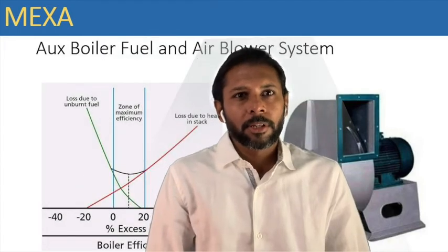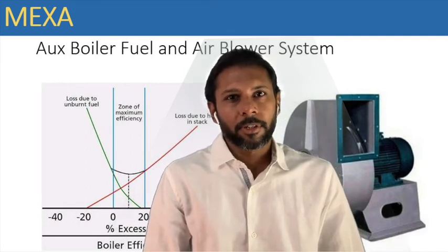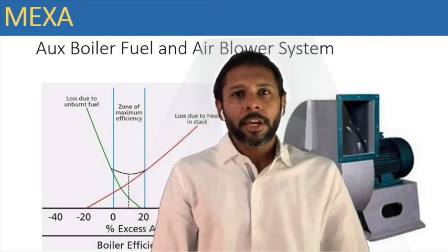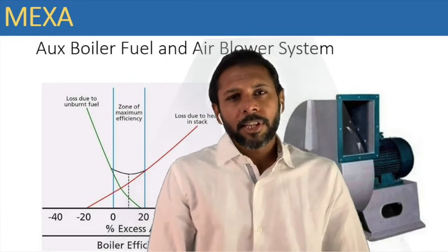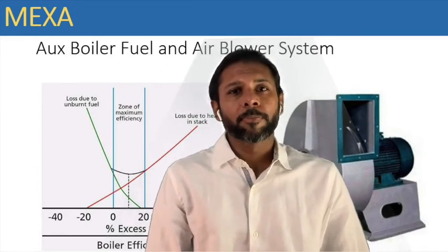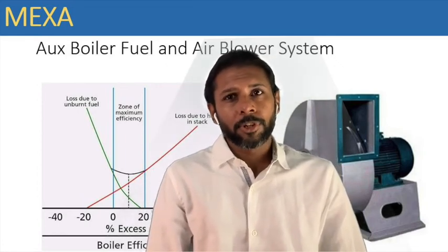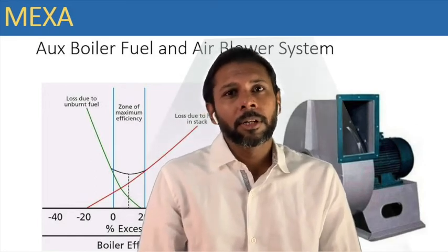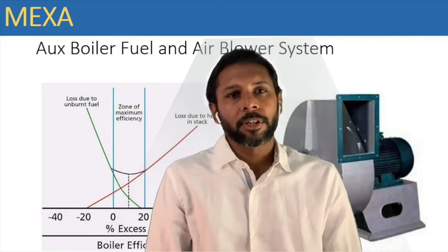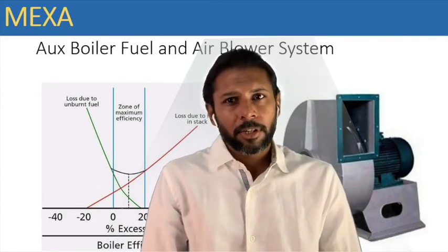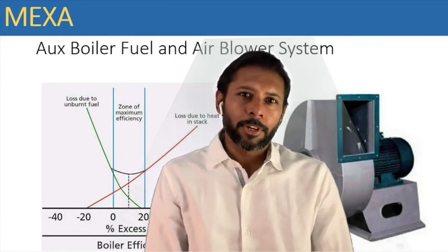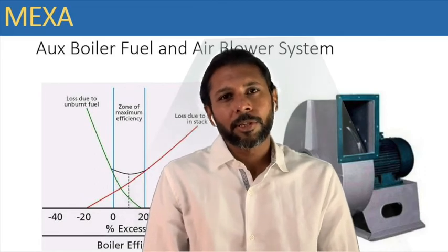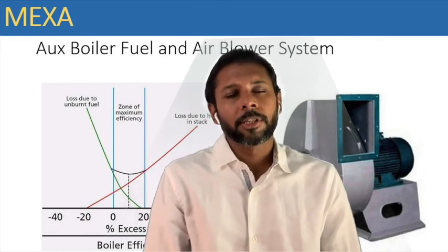Marine boilers are arranged for forced draft. FD fans force the air through the furnace. Several arrangements of forced draft are possible. The usual forced draft arrangement is a large fan which supplies air along a ducting to the furnace front. The furnace front has an enclosed box arrangement known as an air register, which can control the supply of air.